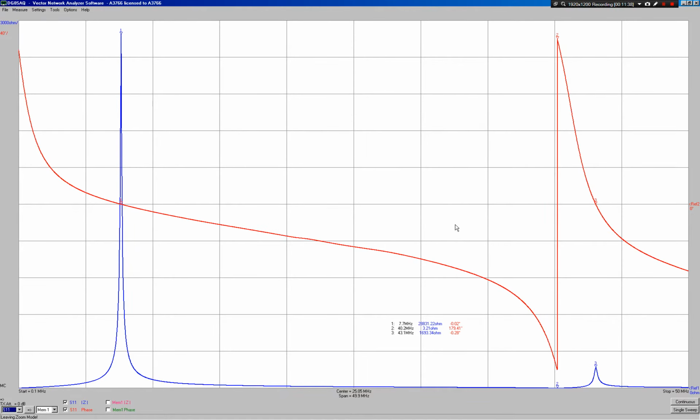Okay, all right, so now we've got to this point, I'm going to reconnect the parallel tuning capacitor. I've got that currently disconnected from the circuit. I'm going to plug that in now. It's the advantage of having these high voltage 4mm terminals, so that you can connect these things relatively easy, which is good in the experimentation. And I've got the tuning capacitor fully out. So that would be less than 20 picofarad load that's placing on the circuit. So let's just do another scan.